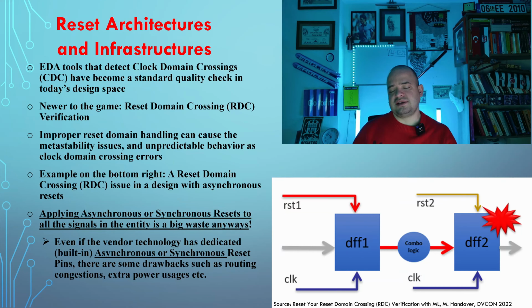Because using synchronous reset directly, for instance, is preferred by Xilinx. Xilinx recommends using synchronous resets as long as you need a reset, but it also has some drawbacks.